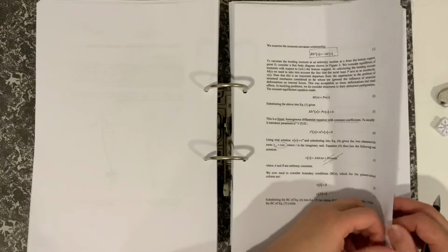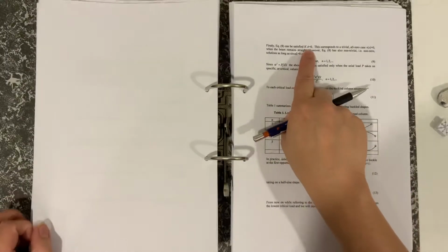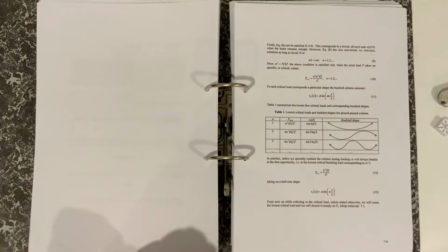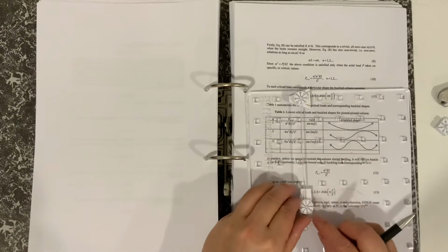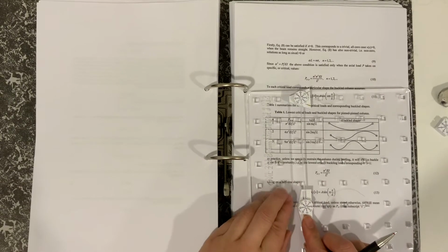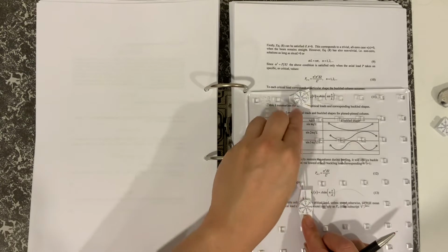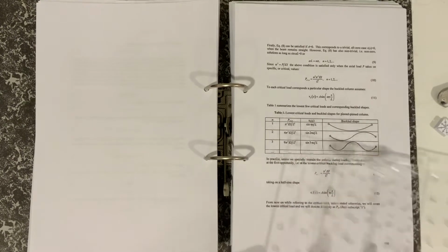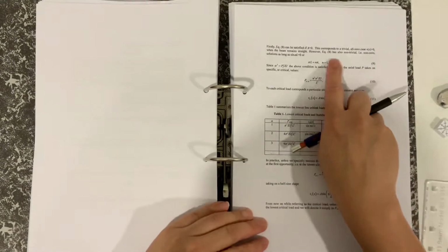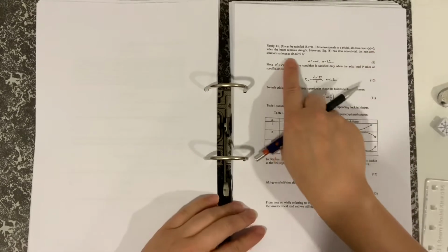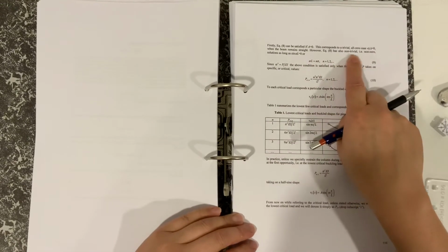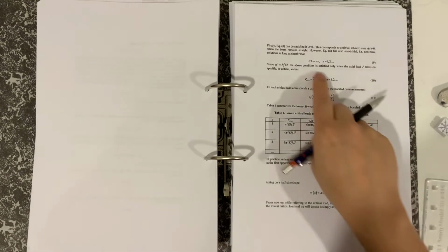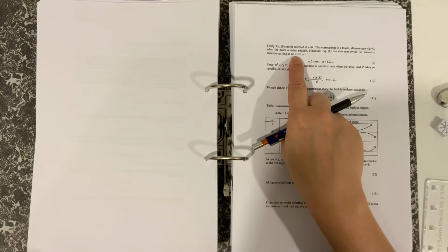So there are two solutions. One of them is a equals 0, and this corresponds to the trivial solution. The trivial solution being, if we just imagine I stuck a really small load on, this is just going to compress in the axial direction, and so there's going to be no buckling. v of x is going to be 0, and the beam remains straight. However, there are also non-trivial solutions, i.e. non-zero solutions. And the non-zero solution is sine alpha L is equal to 0.